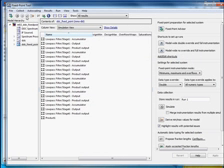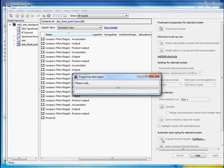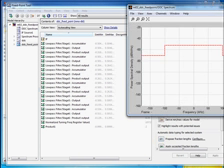Okay. Now we'll go ahead and stop. And we'll ask the tool to propose new fractional lengths, new word lengths that will accomplish the task. So as we scroll through this table, what we'll see is the specified precision and the precision that the tool is proposing. And what we'll see here is these checkboxes indicate where there's a change. The product output, the tool is now proposing that we go from a 55-bit word length to 48. But we also make some other changes through the data path.